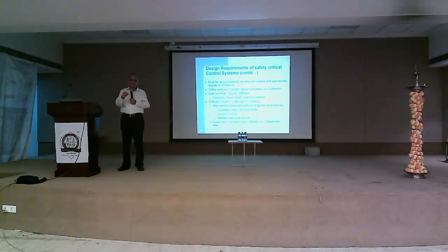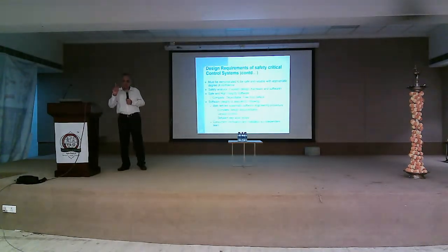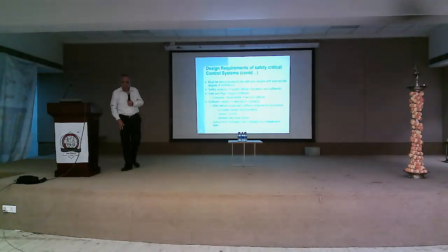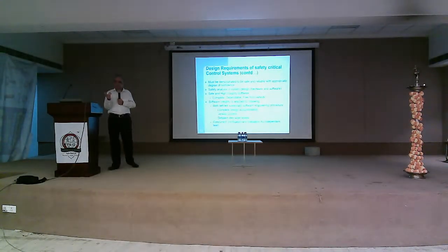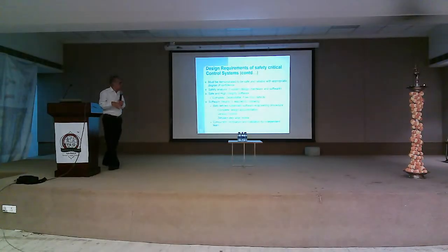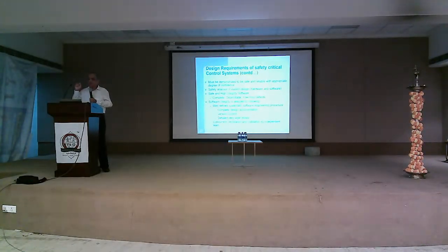Power supply fails, what will happen? Because we have to apply the single failure criterion. If out of 3 systems, 2 fail, of course the protection system is good. But for a single failure, if power supply fails, what will happen? Whether it is separated, whether it will go to a safe state. For all hardware and software things, we do that, make a proper document. If it happens, it has to be in a safe direction.